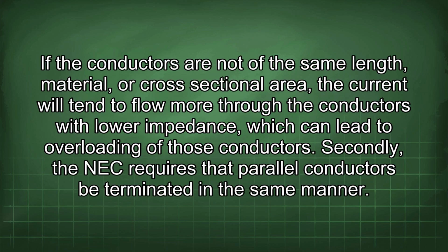If the conductors are not of the same length, material, or cross-sectional area, the current will tend to flow more through the conductors with lower impedance, which can lead to overloading of those conductors.